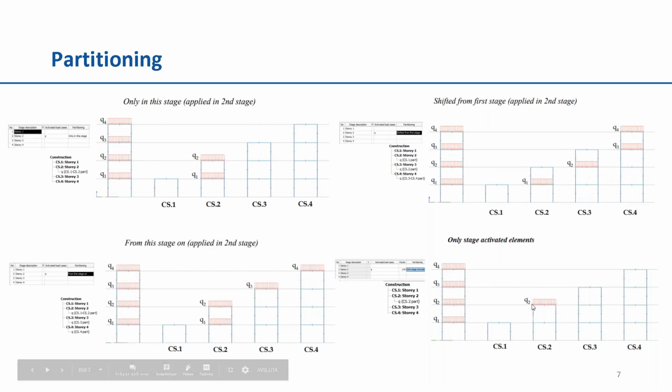So in this case, it's only the line load Q2 because it's applied on the beam that's part of construction stage number 2. So with this option, the load case can occur in more than one stage. And it can be very useful, for example, if you have a composite structure and you have to handle the dead load in a specific way.